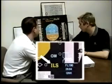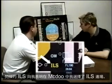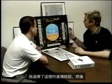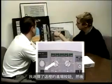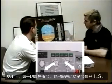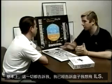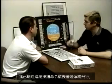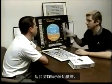What's occurred? Flashing ILS indicates to me that in the MCDU I've selected an ILS approach, I've selected the approach button on, which is over here, and I have not selected the ILS display. Basically, all this is telling me is that I've told the box I want to fly an ILS, I have commanded the ILS to be flown via the approach button, but I don't have raw data displayed.